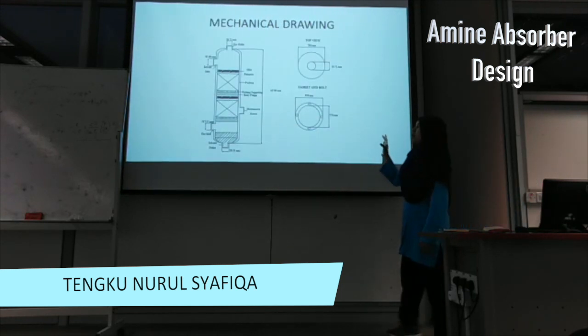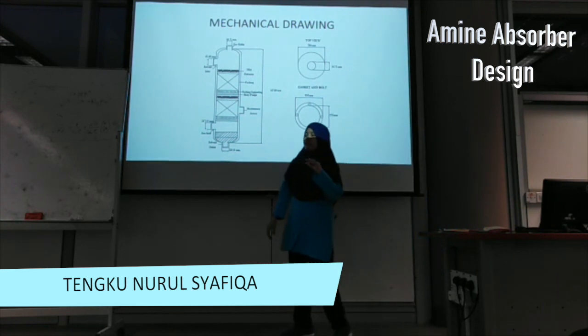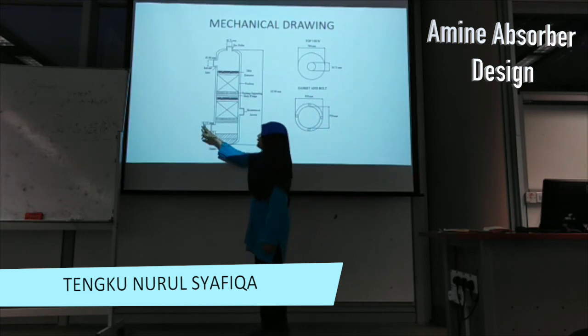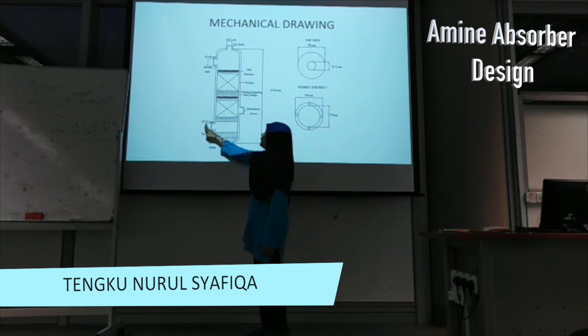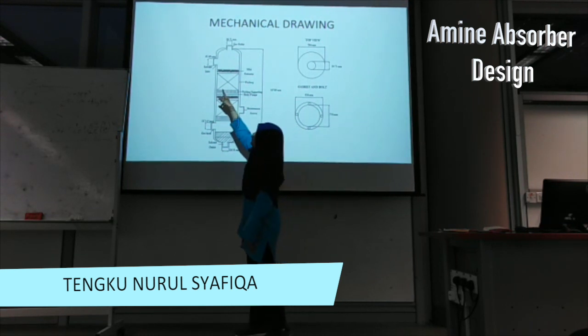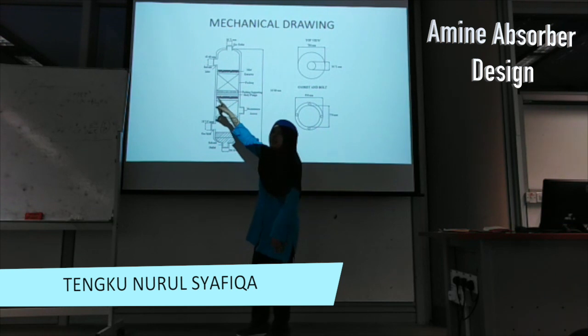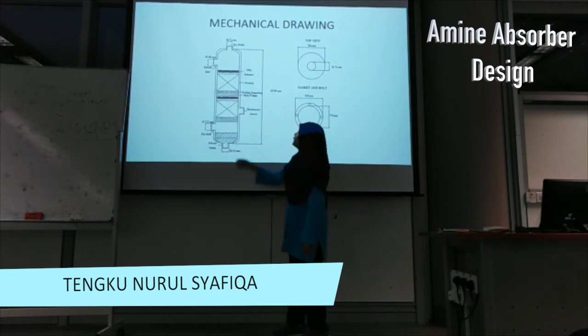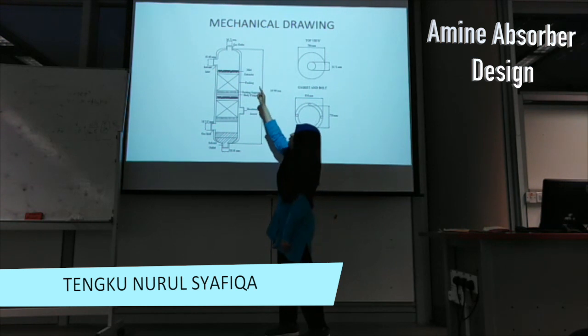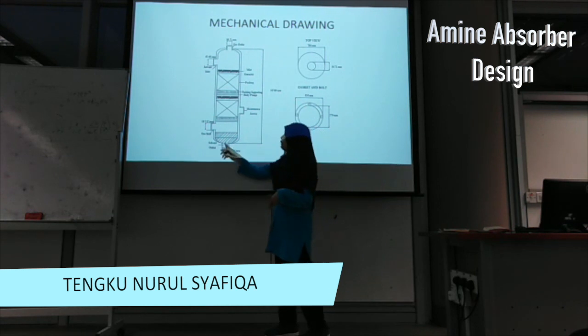So this is my mechanical drawing. The gas stream will be fed to the bottom of the column, which is here, with the size of the nozzle 107 millimeter. At the same time, the dry ethanolamine as our solvent will enter at the top of the column here with 63 millimeter in the inlet. Our resulting desired product, which is sweet gas, will flow out at the top of the column, and the amine solvent will flow out at the bottom of the column.